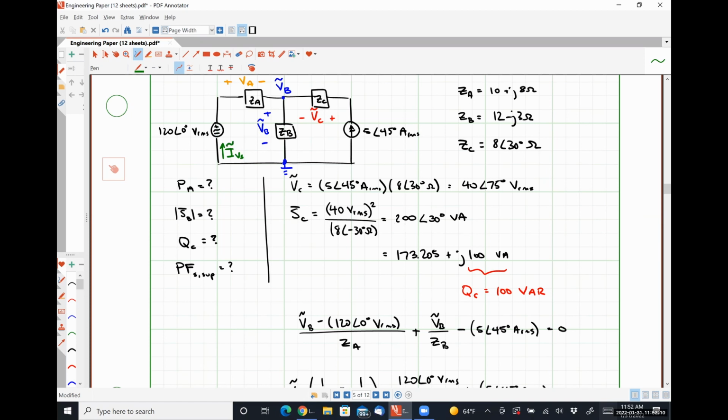How would we go about solving for that quantity? Exactly right. So now that we know what VA is, VA over ZA is that current that we need. And we also need to determine the complex power, or the power factor at which the current source is supplying. So I want the current to be flowing into the negative polarity terminal. So let's call this voltage negative plus VCS. How would I go about determining that quantity?